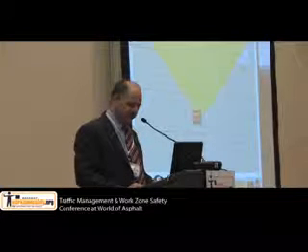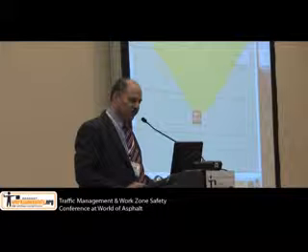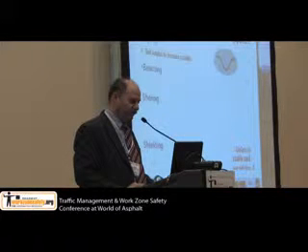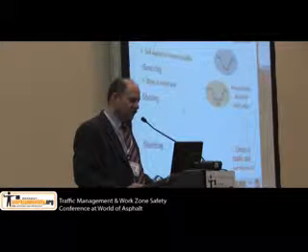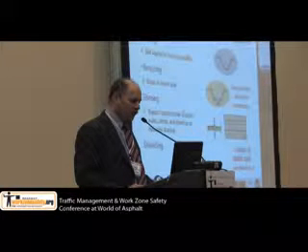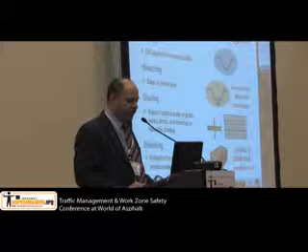We have question marks all over this to define what these things mean, to explain to somebody what it will take to actually protect people in this system. You can also bench the soil, where you have steps in the trench wall. You can shore it, or you can provide shielding, a trench box.